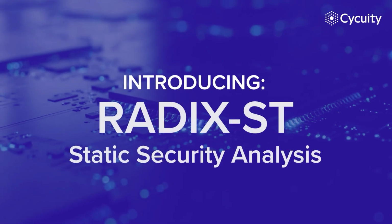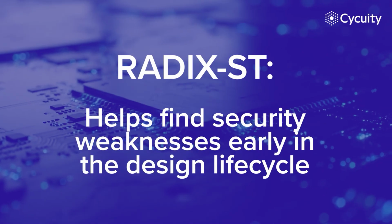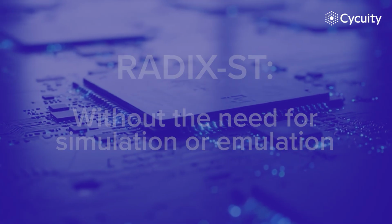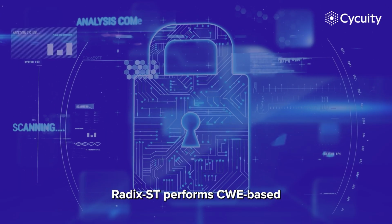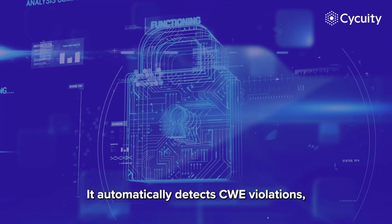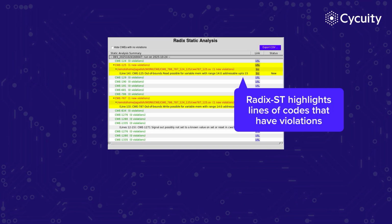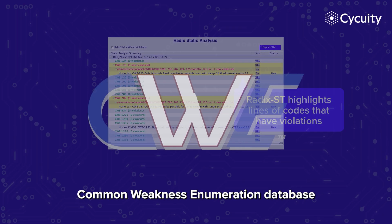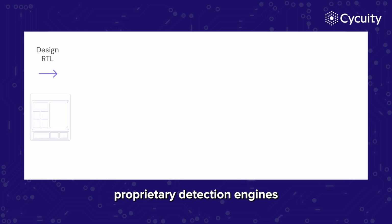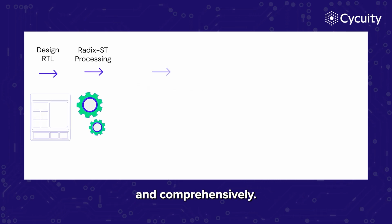Introducing Radix-ST, the static security analysis tool that helps find security weaknesses early in the design lifecycle without the need for simulation or emulation. Radix-ST performs CWE-based static analysis directly on RTL source code. It automatically detects CWE violations, pinpoints their exact locations, and maps them to the Common Weakness Enumeration database for easy reference. It leverages proprietary detection engines to identify weaknesses efficiently and comprehensively.